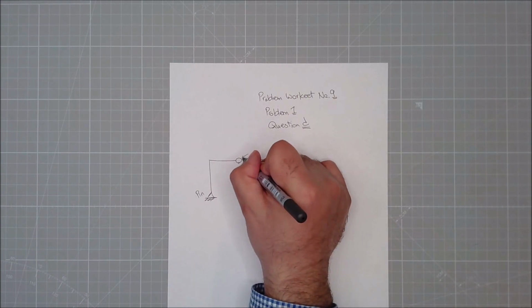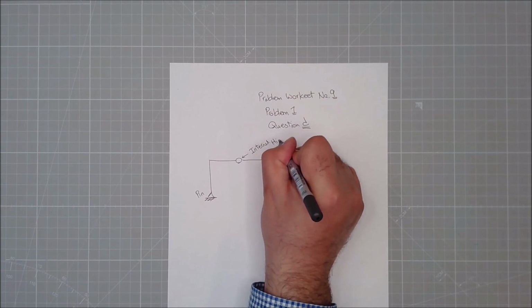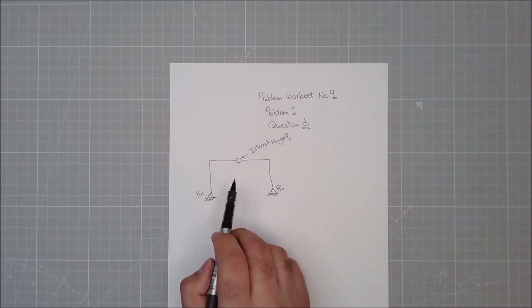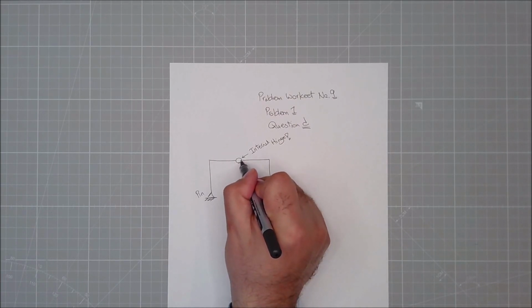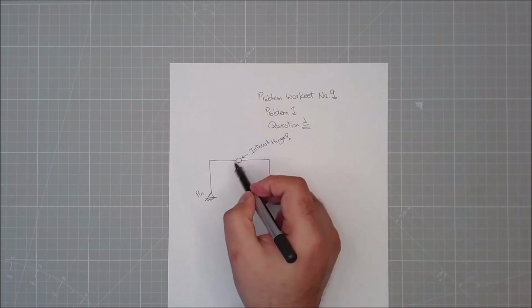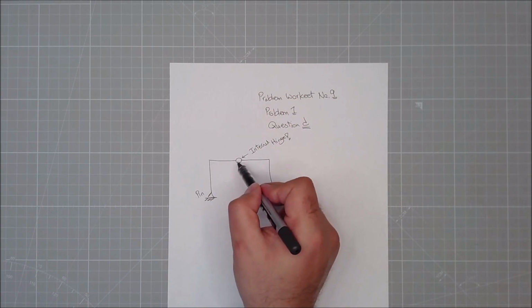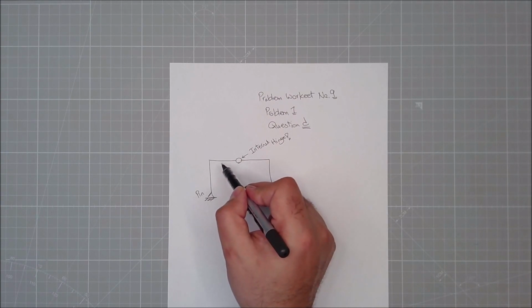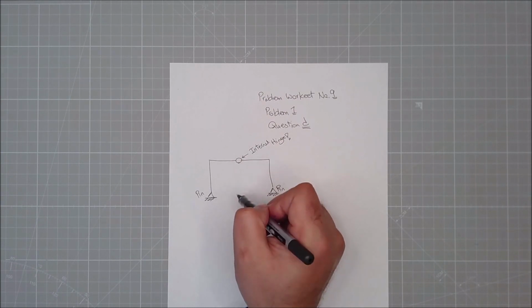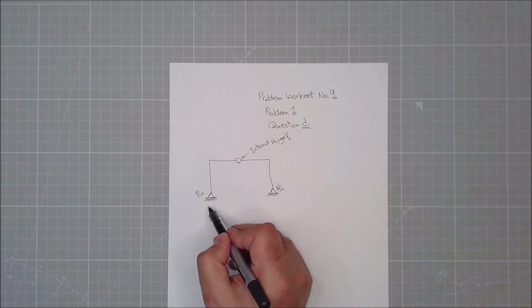So this is an internal hinge, which, remember, has moment equal to 0, so it doesn't allow any transfer of moment. But because it's in the middle of the beam, if the whole beam goes to the left, the hinge will go to the left as well. If the whole beam goes up, the whole hinge will go up as well. So it doesn't act like a pin which is fixed to the ground.